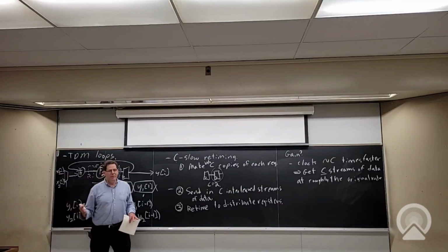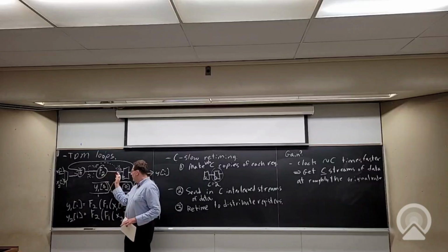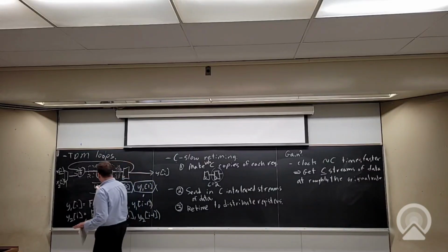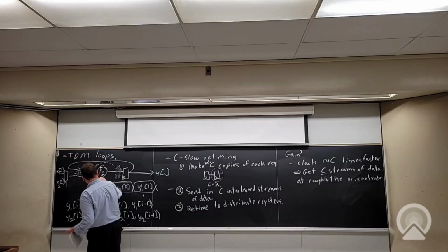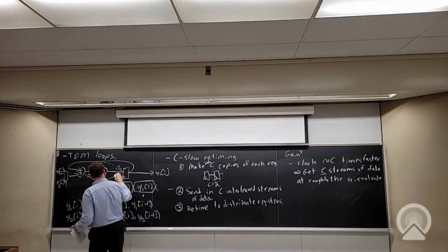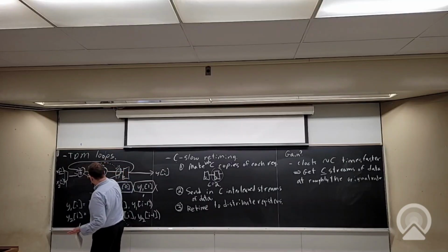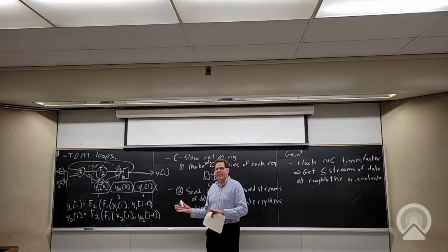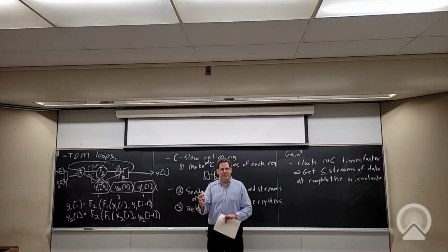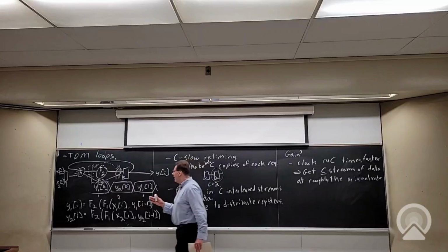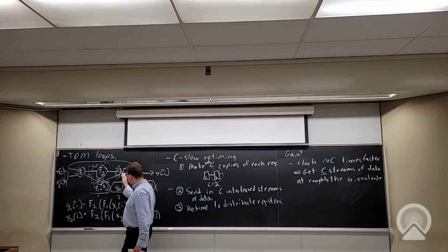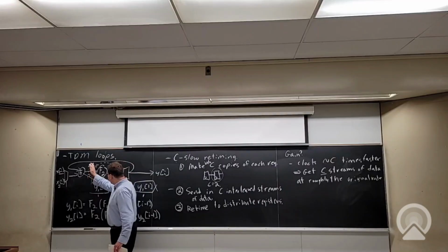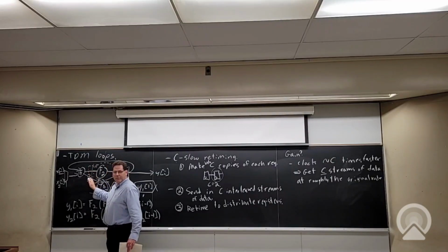it's more disruptive. As it does that, here I've shown you that this register there's only one copy. But if I actually had like an F3 here, so I did something like this, and there's another block here, retiming this register to this point actually duplicates it. Okay, I have to, because what retiming is doing is basically taking a cut and changing it to a different cut. Okay, so I basically move this register across this logic. I have to take all the places that it crossed, and I have to put registers there.